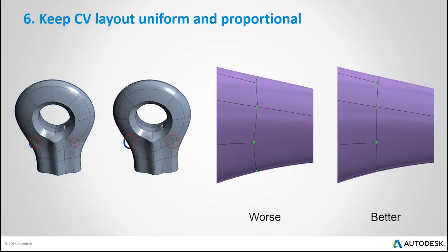You can also try and keep things as uniform as possible. There is what we call a flatten command. So if you look at the one labelled worse, you can see the line's fairly wavy. After you've used the flatten command, you can see on the right hand side it's better. So that'll give you a better finish on your component once it's done.